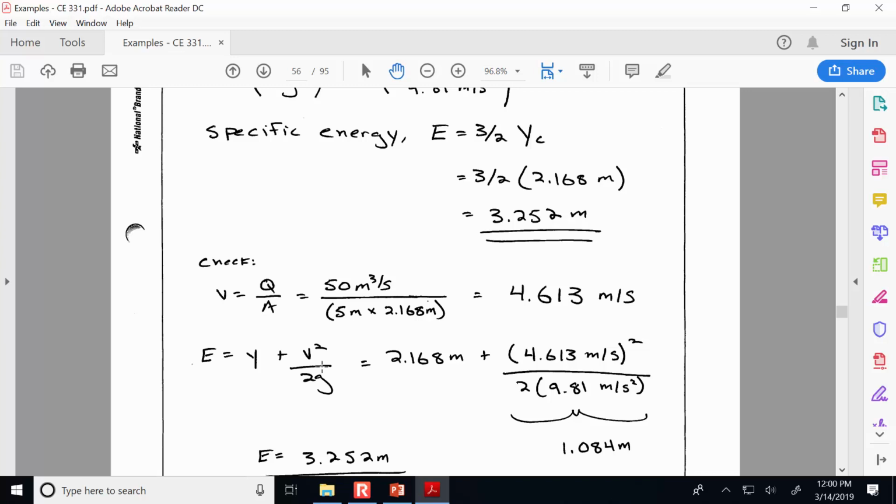Now, why does it matter? We're going to look really in depth at chokes on Tuesday. Like, if you keep putting more and more obstructions in a channel, like piling up logs, eventually the water isn't going to have enough energy to make it up over that obstruction. There's some critical height of how tall that obstruction can be.